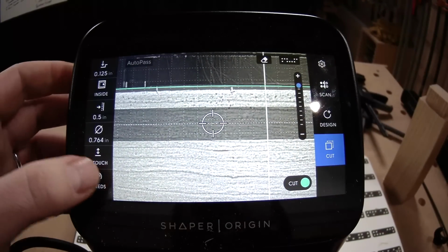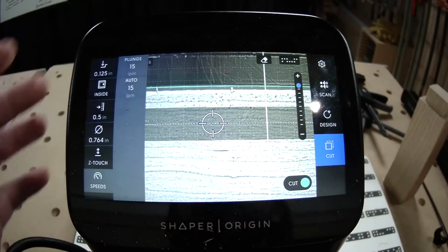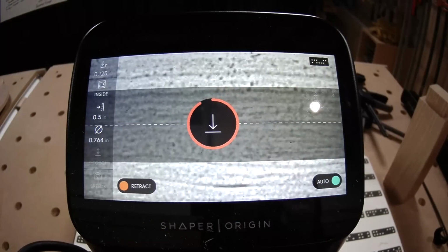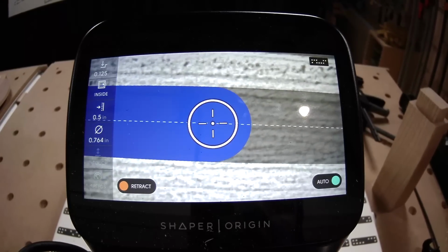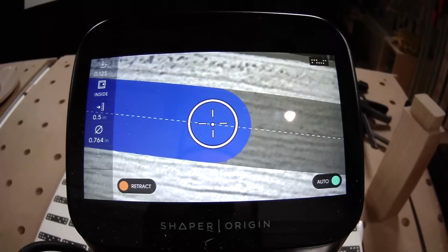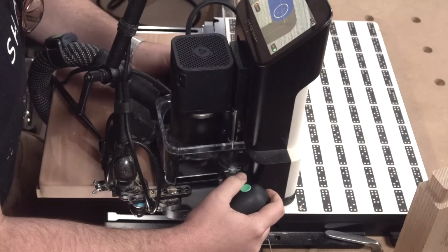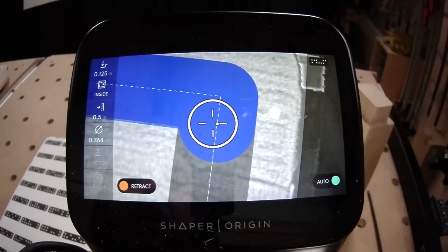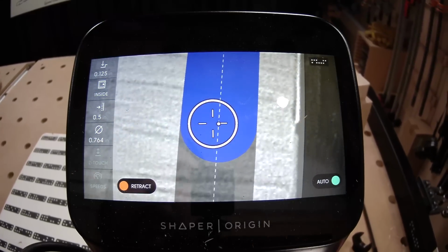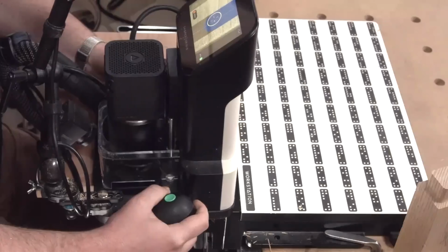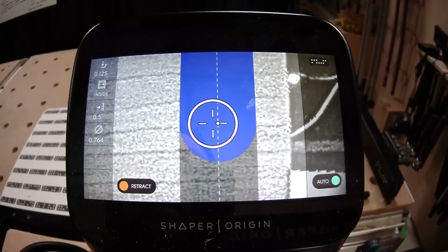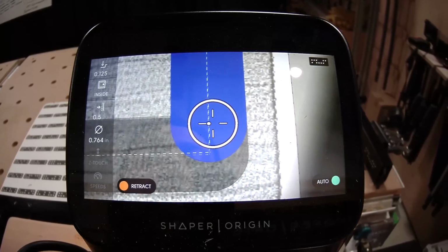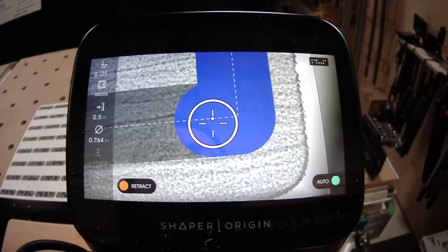And, one note, depending on the depth you're doing this groove, you might want to cut more than one pass. You could always activate AutoPass and lower that depth of cut so you can make a bunch of more shallow passes. It does two things. One, you're putting less load on the bit as you go through your material. But two, as you go deeper, you're actually widening your path. So instead of doing it in one go, you can get a little bit better cut quality sometimes because you're widening at the same time. For this it's like a roughing pass versus the finishing pass. Exactly. And we do the same thing for engraving as well.